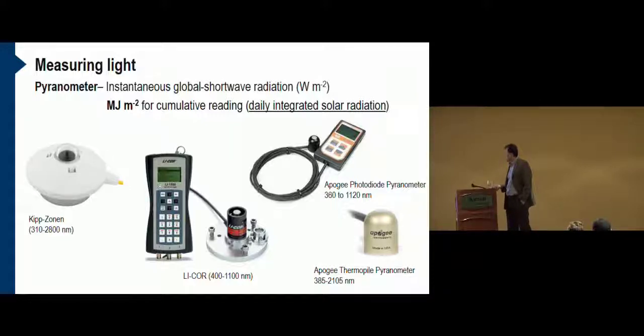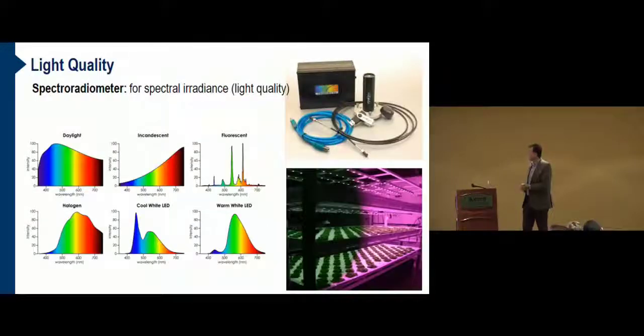There are some other models available also on the market using thermopile-based measurement with a fraction of cost compared to traditional thermoelectric-based sensors, as you can see here. So you need to decide on what type of measurement you would like to perform, the accuracies you want from a given sensor, and also the cost will play a role at the end to make a decision.